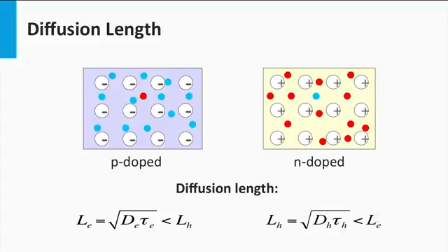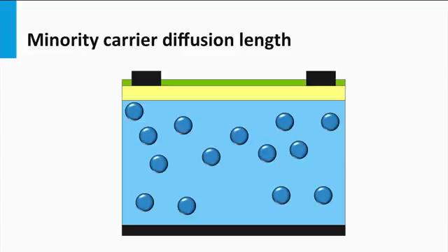Why is that the case? This is demonstrated in this simple animation. Let's consider photons that would penetrate far into the absorber layer before they are being absorbed. We want these charge carriers to be separated at the p-n junction or the back contact. But let's assume that these charge carriers are excited at a depth deeper than the typical diffusion length. The excited charge carriers recombine within the typical diffusion length before arriving at the p-n junction.